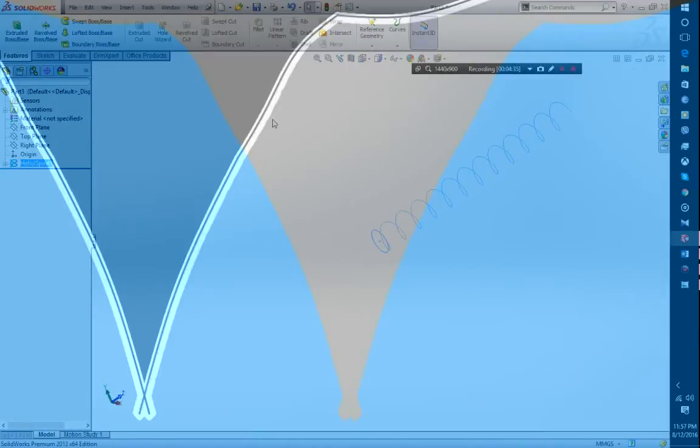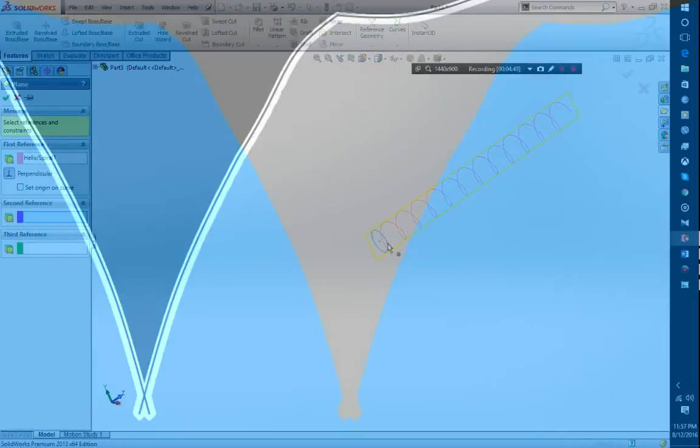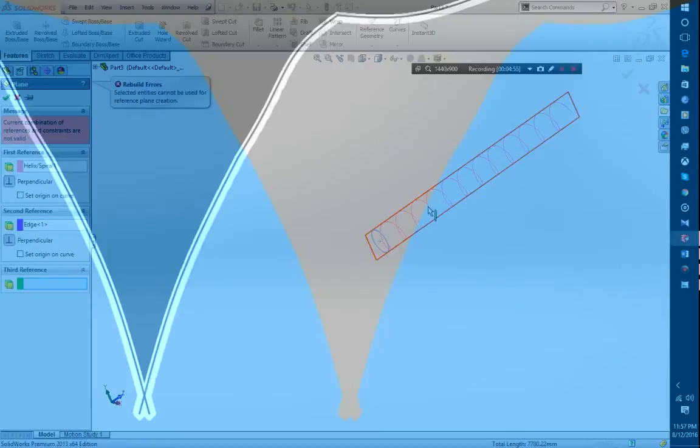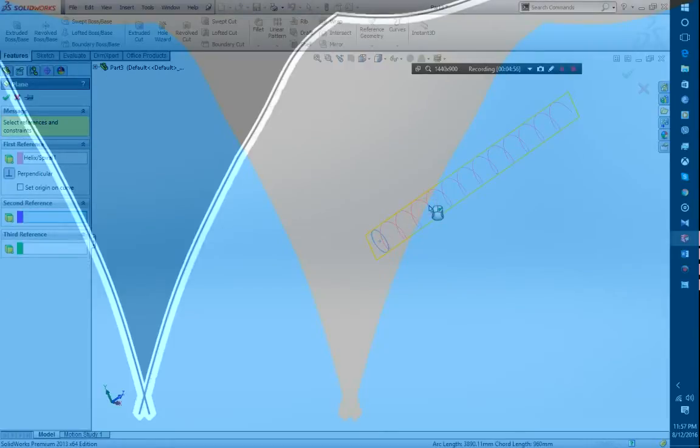Now in order to put the wire, I will need a circle from where the wire will generate, and put it on this point. So I will go to the plane option, and it is already selected: any point on the helix. Let me show you again. If I choose this, it will go away. Oh no, sorry, I chose the edge actually. It will automatically choose, I guess.